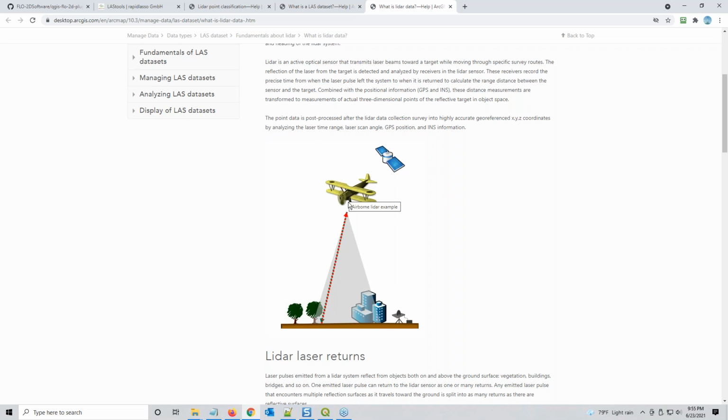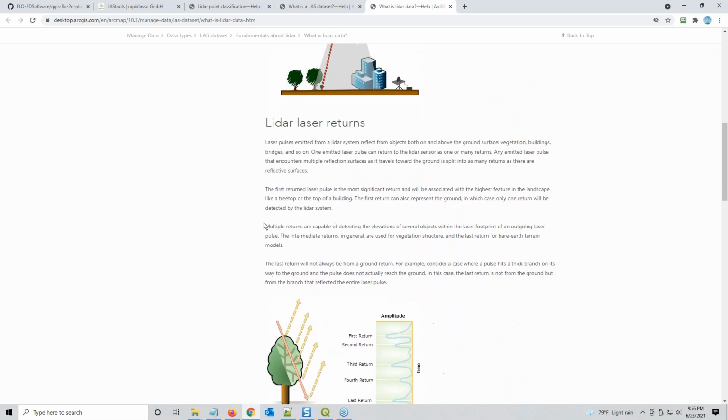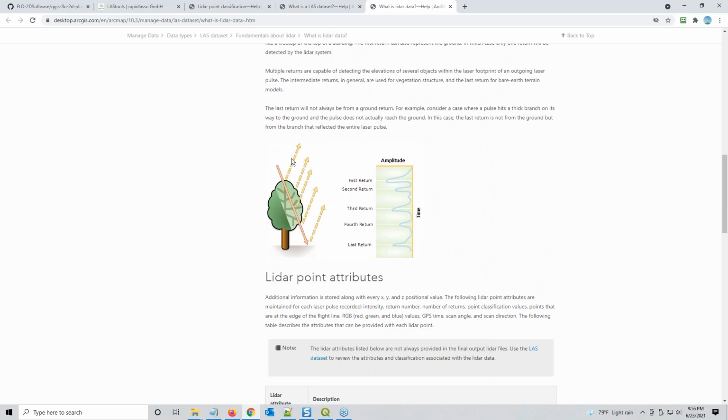It could be a drone, an airplane, or a regular plane, and it's going to fly straight lines across the ground, and then shoot the ground with the laser, like millions and millions of times. The paths that the laser covers overlap, so every time it does a swipe, it's going to hit every point, possibly more than once. Once you see your point, it might bounce back at a different